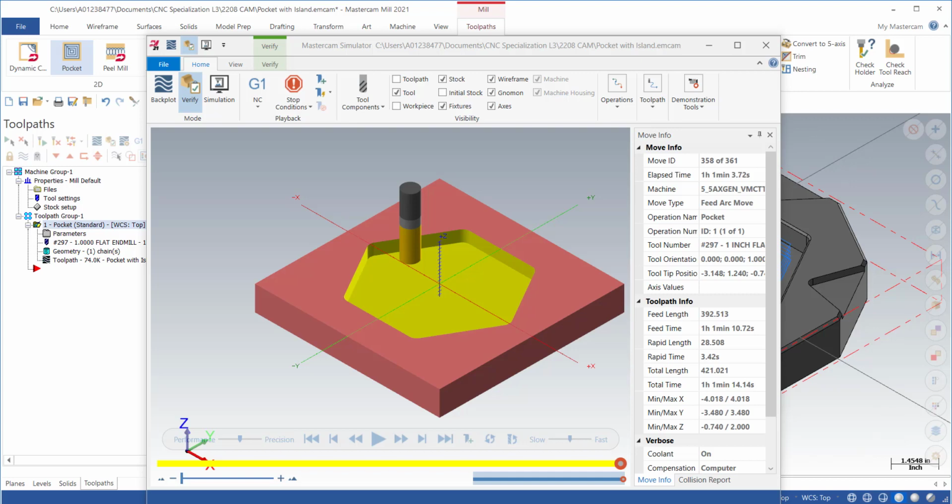Okay, so next step, we're gonna pick our finishing tool. But with the finishing tool, I can't just go finish it off because there is more material in the corners, and that will be too much maybe for the finishing tool to take care of. So we need to first clean up those corners with a smaller tool so that it can take off that extra material. Then we would add a finish pass. So that's what we call remachining.